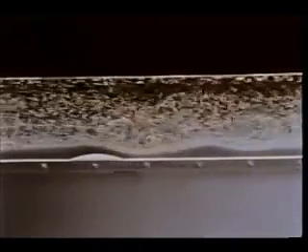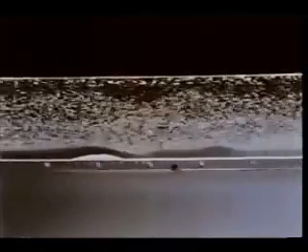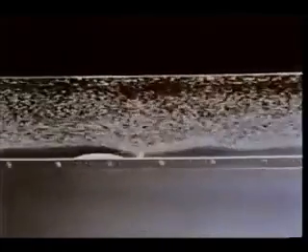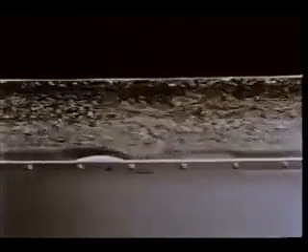When the Froude number is low, but the obstacle is large, the flow pattern again has a small scale, but is of a very different character. The approach flow consists of a number of jets moving rapidly toward the obstacle, sandwiched between layers of fluid that are stagnant with respect to the obstacle.